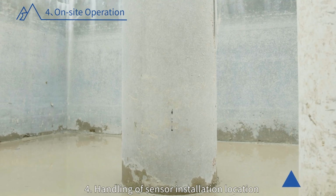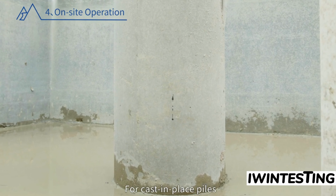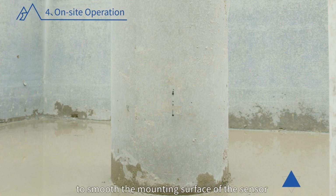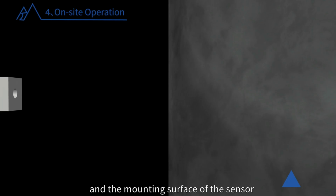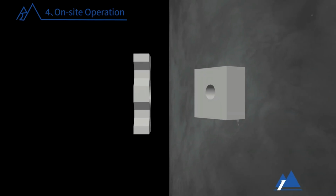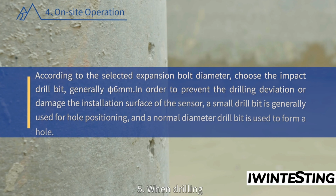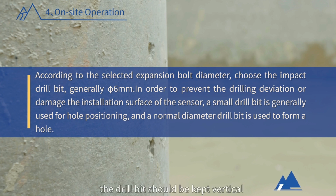4. Handling of sensor installation location. For cast-in-place piles, the grinder should be used to smooth the mounting surface of the sensor, and the mounting surface of the sensor should be parallel to the axis of the pile. For pre-cast piles, optional smooth surface installation. 5. When drilling, the drill bit should be kept vertical to the side surface of the pile.